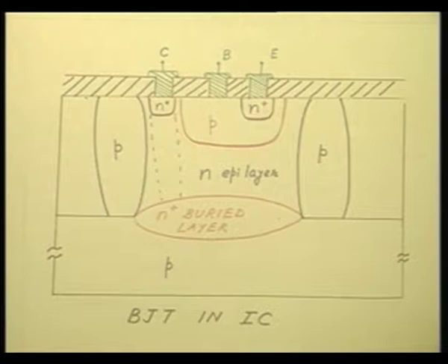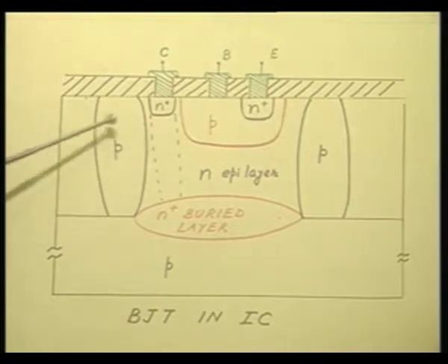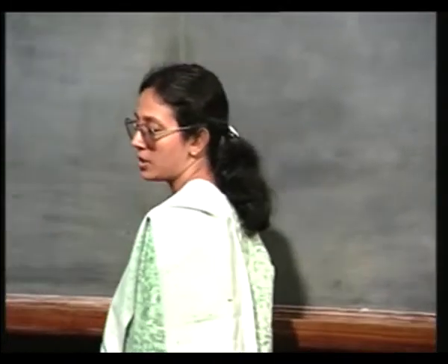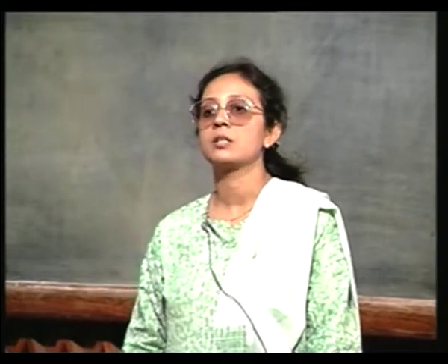Okay. So, this is, as I said, a comparatively older bipolar junction transistor which uses junction isolation. That is, this reverse biased PN junction is used as the method of isolation. Okay. Now, let us look at this junction isolation technology, because immediately after the buried layer we must concern ourselves with the junction isolation. Now, you see I am still talking about the older day technology.